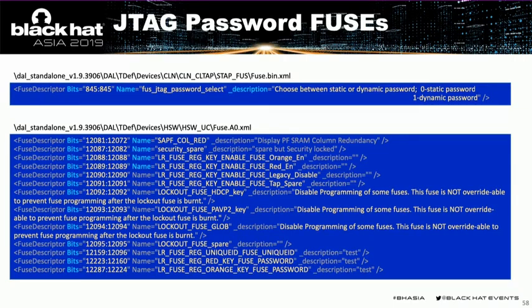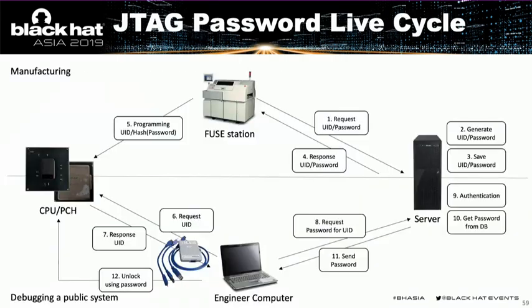It's a very old platform, but in another configuration file we found that the CPU has a fuse JTAG password select, and you can choose between static or dynamic passwords for JTAG. I remind you that if you have red unlock, you can do anything with your system. You can read memory and bypass all protection techniques without any problem.